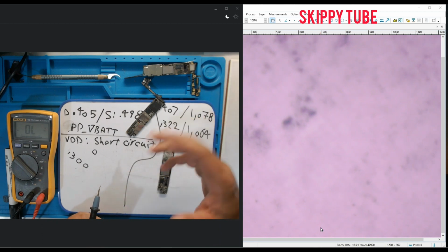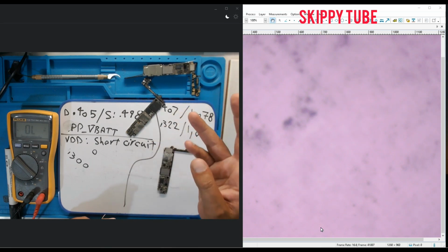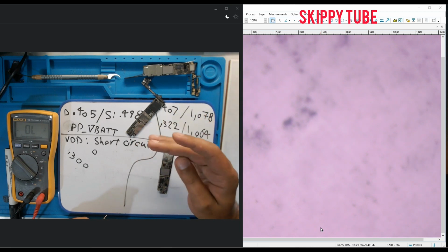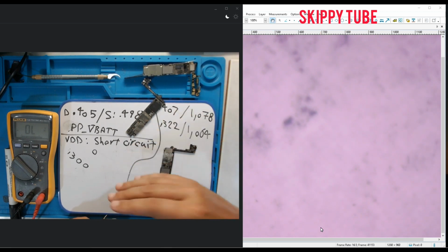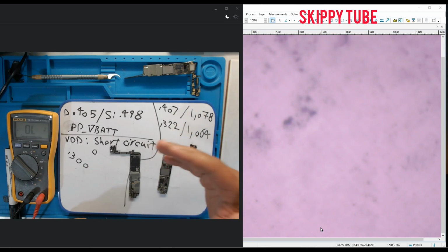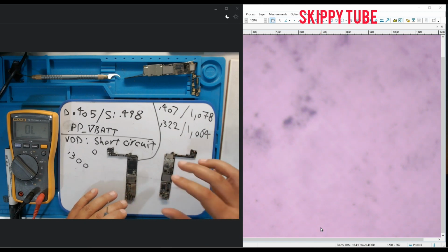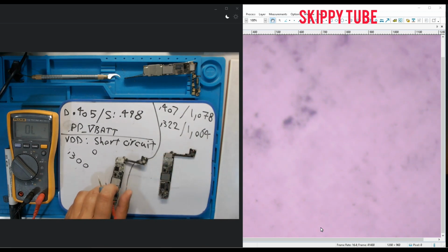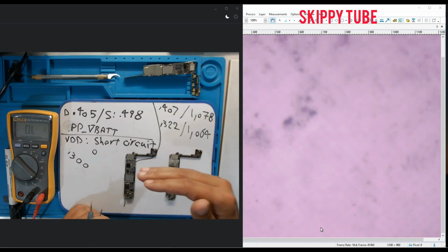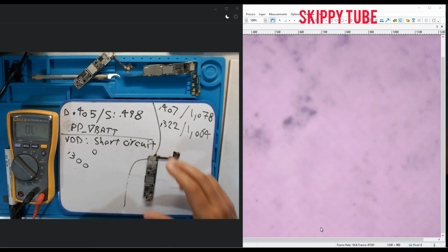Other times, the phone has a different level of issue, and at that time you need a schematic diagram, experience, and knowledge about electronics and blah blah blah. But 70% is easy to find the issue, and in the future I will make a lot of videos to explain how to find the issue. Now we're going to check the two phones and compare the 1.8 I/O and 1.8 SDRAM. This is the faulty or abnormal motherboard.